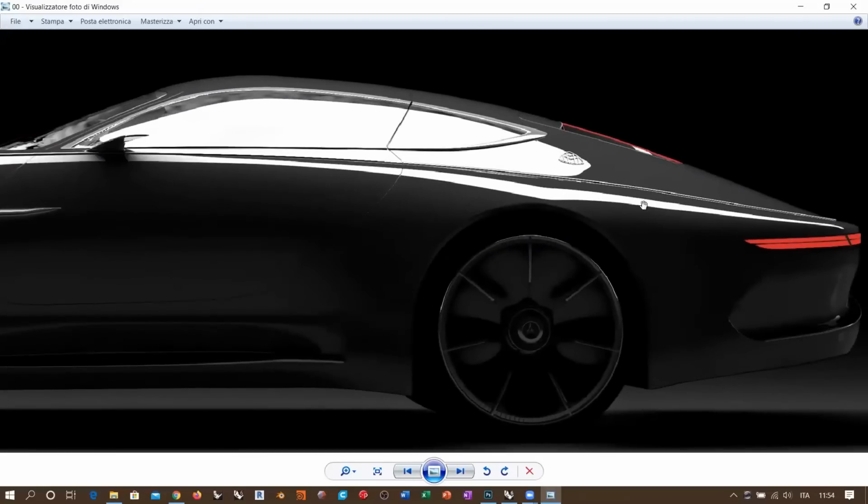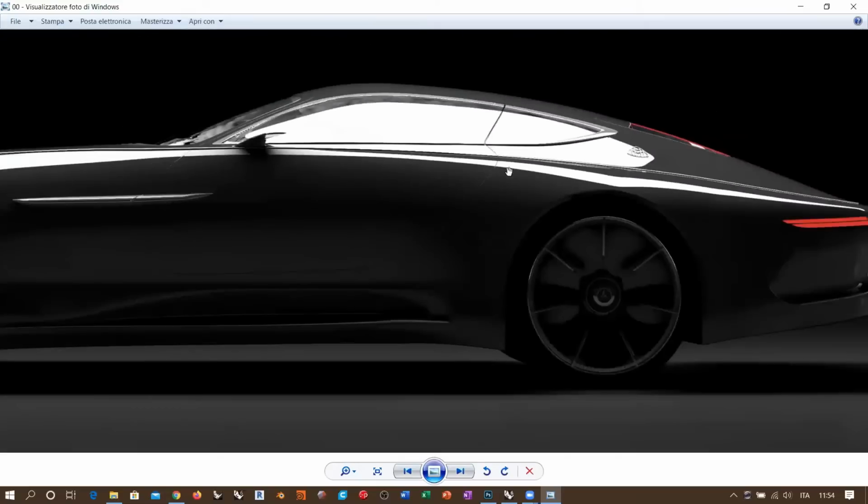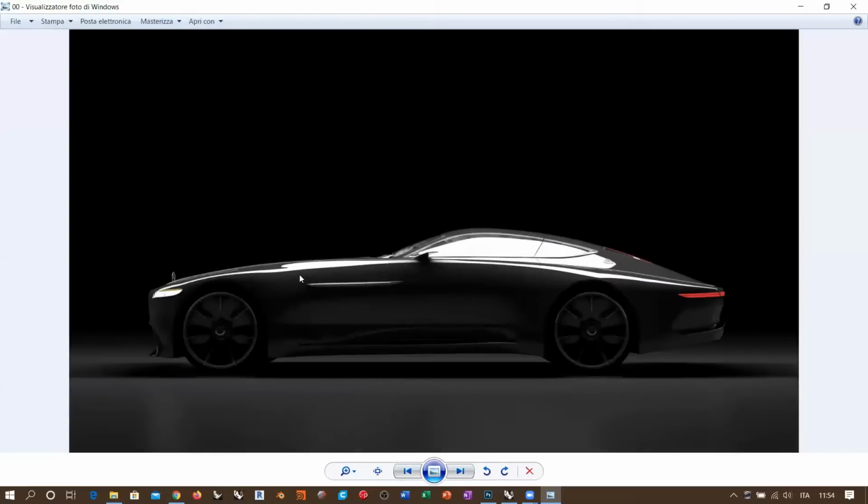Once I had the final shape, I just trimmed the surface with a trim line. Okay, so this makes this part of the surface perfectly continuous with this part because they are part of the same surface. So that's why this method probably is the safest method to obtain a perfectly smooth and aerodynamic surface. But it sometimes takes a lot of control of the topology in order to get to this type of final result.